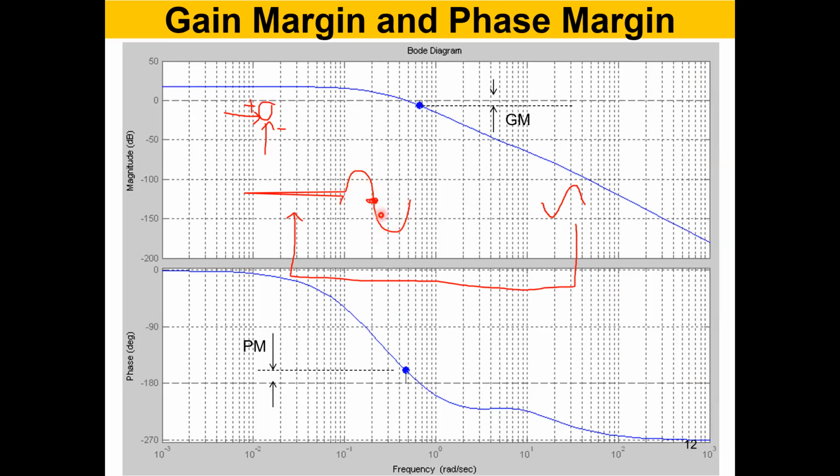So when this signal, at between 0.5 and 0.6 radians per second, passes through the block, passes through the system, it becomes like this. It weakens, right? It drops in magnitude in addition to being 180 degrees out of phase. Now, when you feed this one back, even though it is a bad idea, you will be safe. Why?